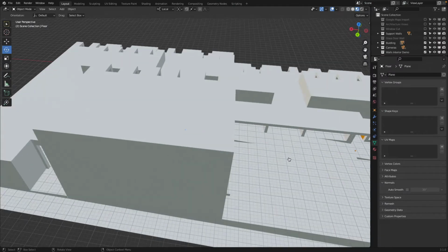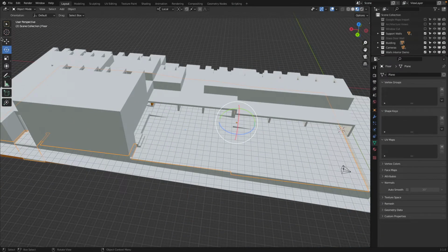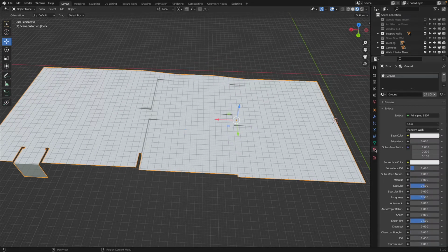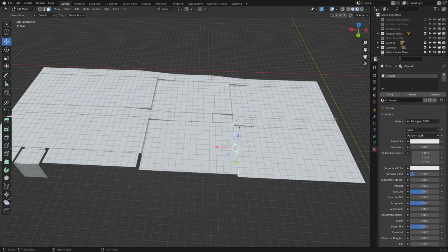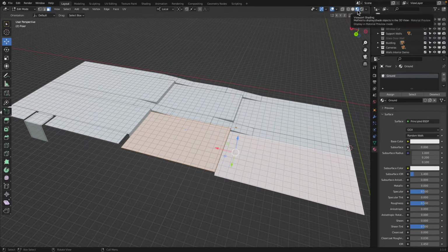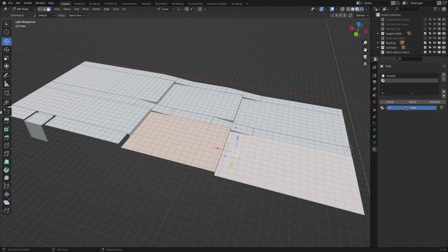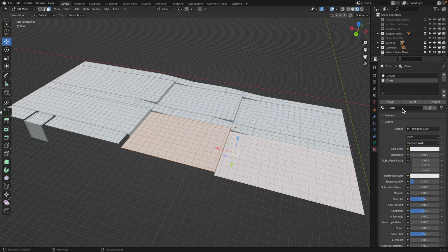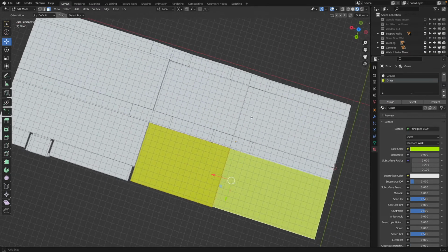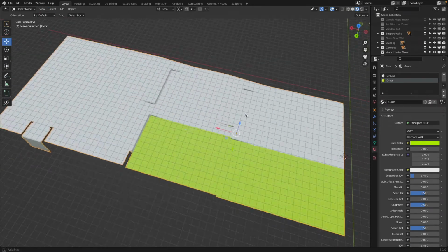So to Blender, we will select the floor, Shift H, hide everything else, and then we will give this a nice green material. So to materials, I already have a ground material. I will go into edit mode, select this and this face, and turn on the material preview. There we are. Plus new, grass, a nice grassy color, and then click assign. There we are. Okay.